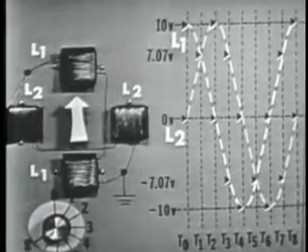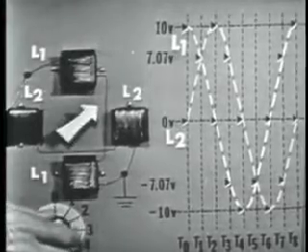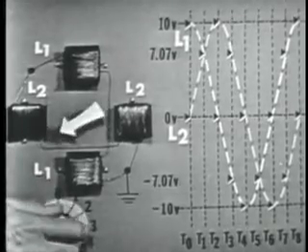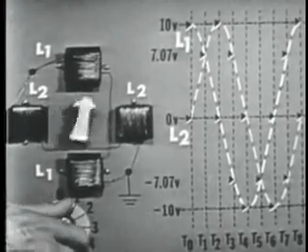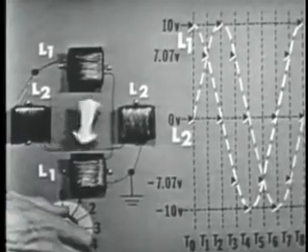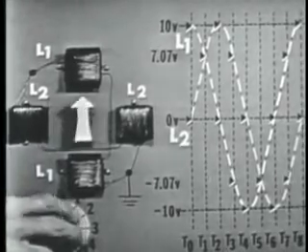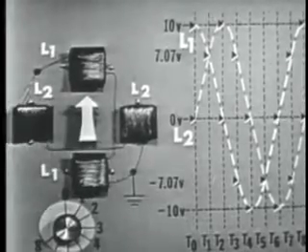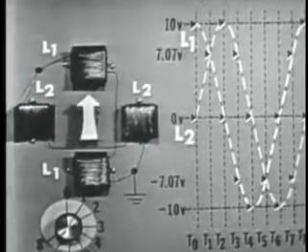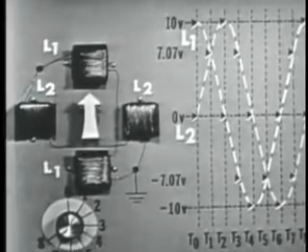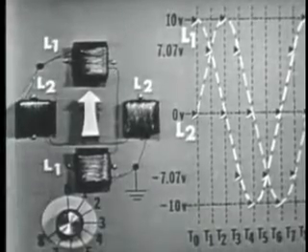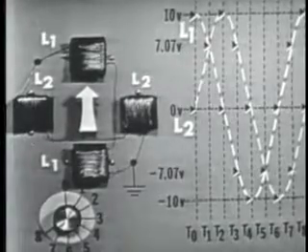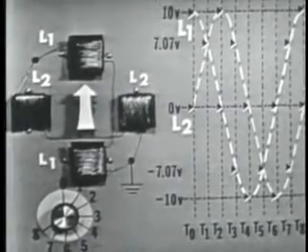Item 7 shows you how one complete revolution of the magnetic field is accomplished by applying these out-of-phase voltages to the stator windings. Now, you can study this very, very carefully so as to fix the principle in your mind. By the way, we might point out, Tom, and once again, that you can apply the left-hand rule to all these coils and prove precisely what we've said, right? We can develop a rotating magnetic field. I'm certainly glad you said that. A rotating magnetic field that induces a voltage in the rotor, causing it to become an electromagnet, which will follow the rotating magnetic field.